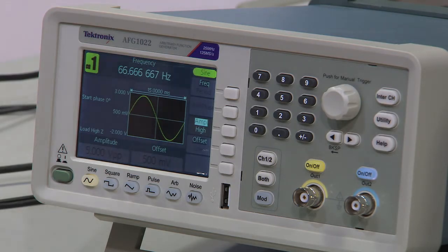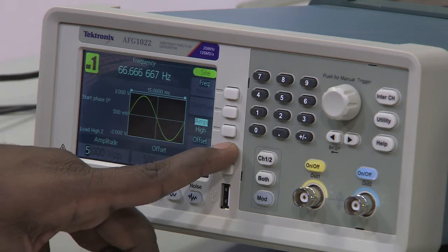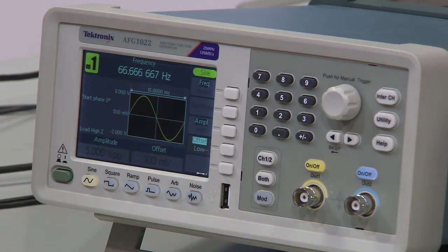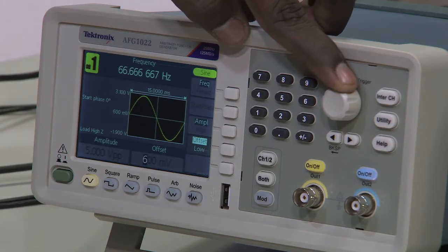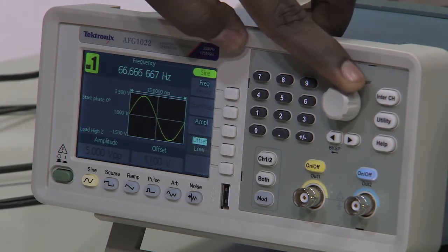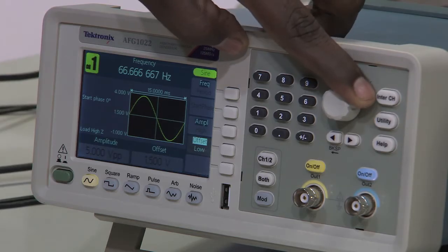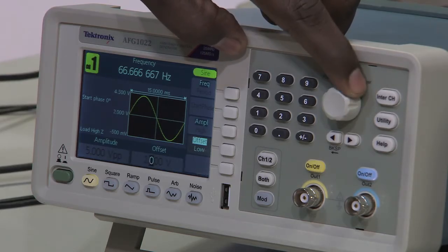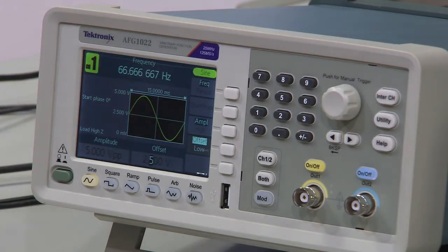Next one please. With the next white button, if you want to create an offset, you can create an offset by again changing the manual trigger or by using the display key or the other push buttons. Alright. So, if you see the offset, you can clearly change it. Earlier it was minus 2 volts to 3 volts, now it is 0 to 5 volts, it is still 5 volts peak to peak, but now it is from 0 to 5 volts. So, we can change the offset. Alright, what is the next one please?